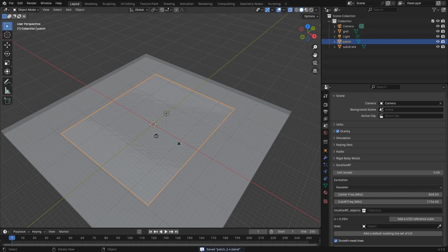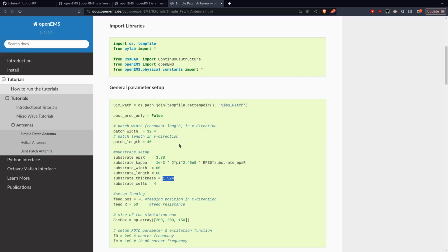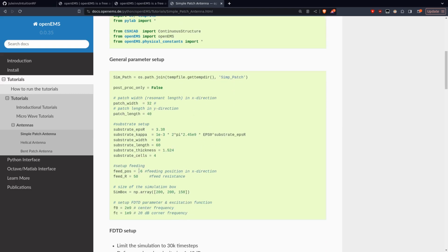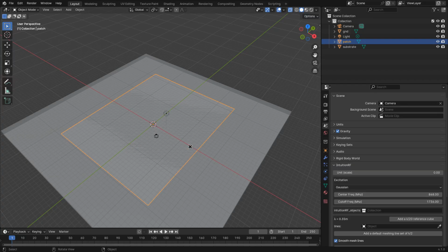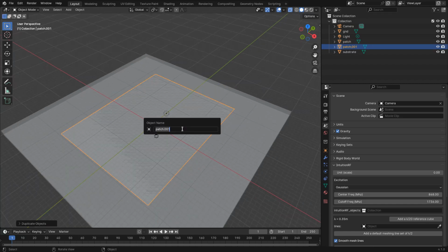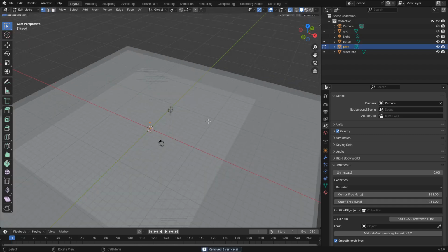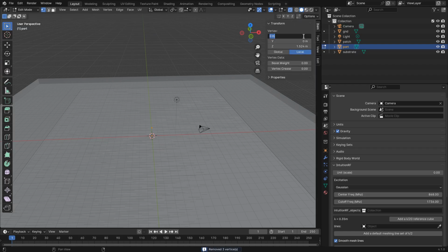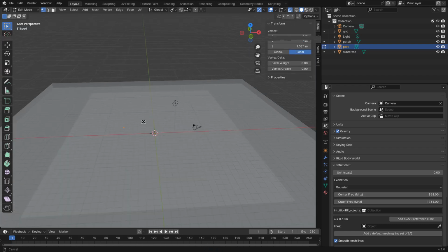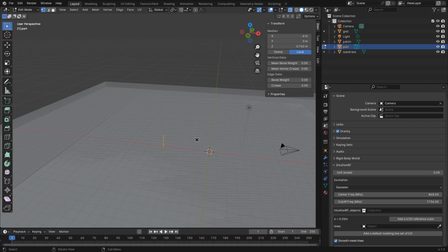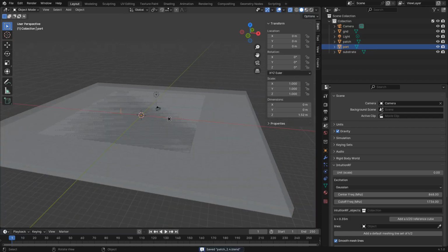And now we have a port that is a lumped port. It's at X position -6. So let's do this. I'm going to duplicate this, rename it. And now we have a single point. We put it at -6 on the x-axis, extrude vertically and go to the ground like this. Okay, so that's our model complete.